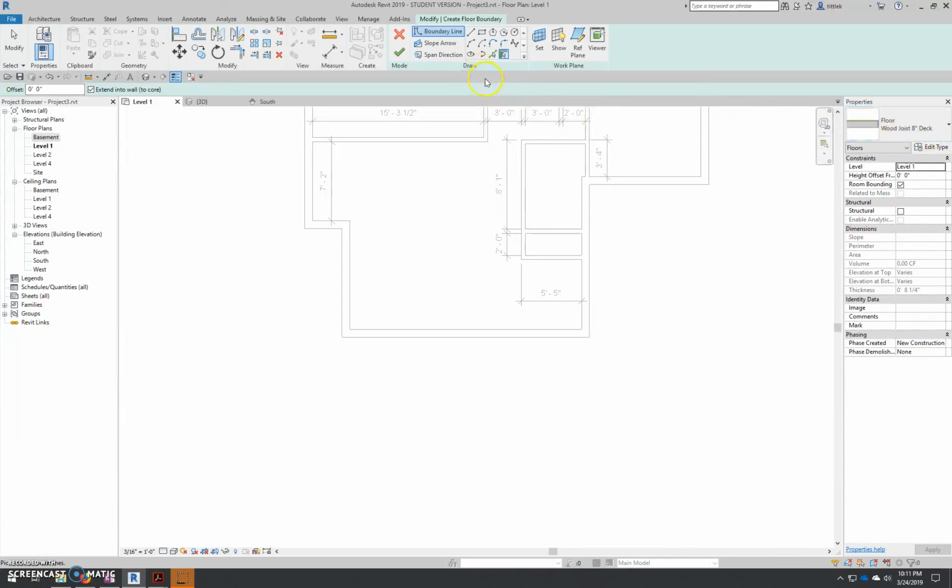And we are not going to pick the walls anymore. We're going to draw the outline. So we're going to click the line button. I forgot to check my other constraints. I didn't really forget. I just know that by default this sets it at 0, which is what we want. We want it to be 0 inches off of level 1. We don't want to create any offset, and we're going to use the chain command. And we're going to come in here, we're going to draw right along our exterior wall. And we know it comes out 6 feet.